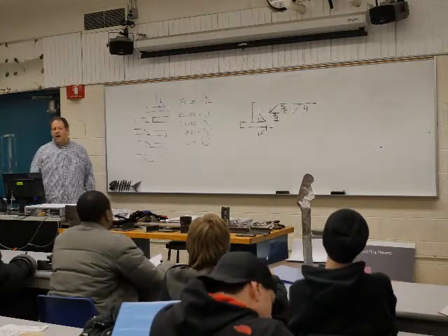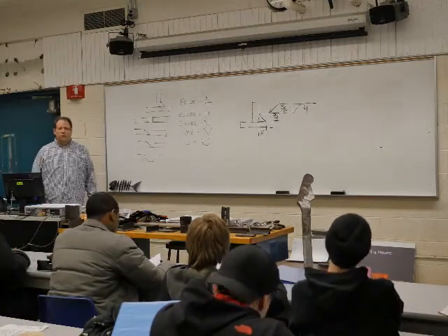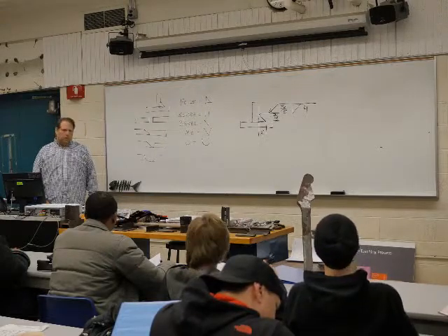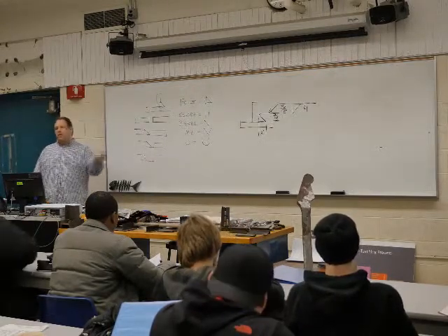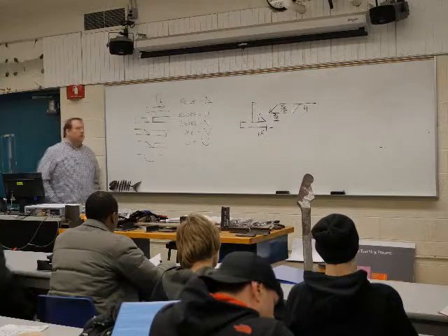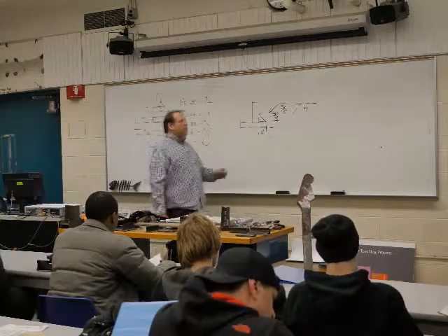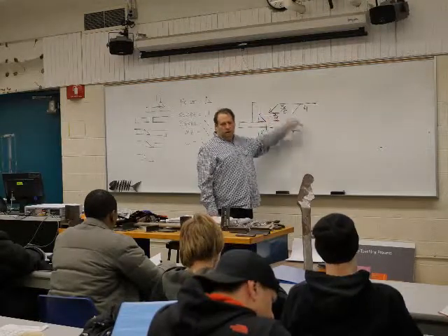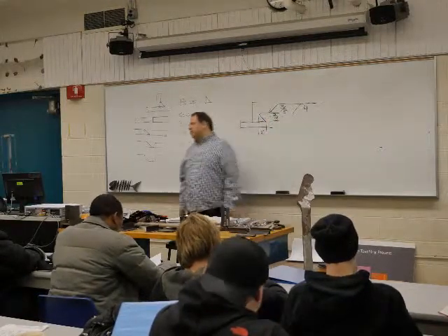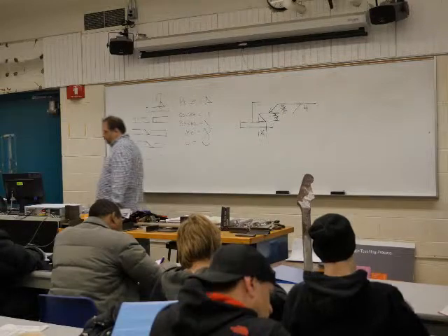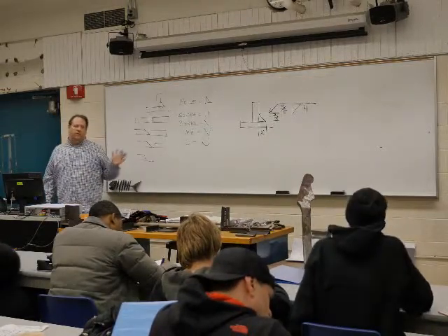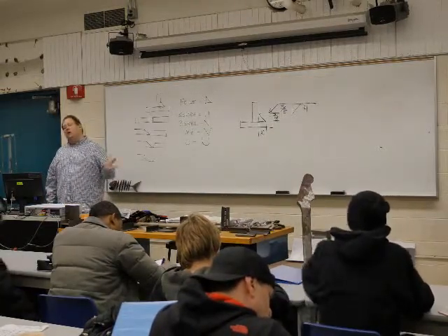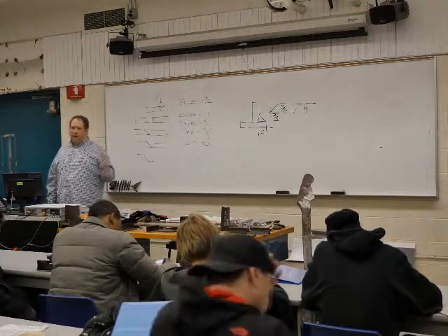Since we already got the size of the weld, what do you think the 4 would stand for? Length of the weld. Yeah. So we got the size of the weld, now we got length of the weld. And this would be 4 inches generally, unless we go into metric, and then it's going to be different. So before the fillet weld symbol, size. After the fillet weld symbol, length.